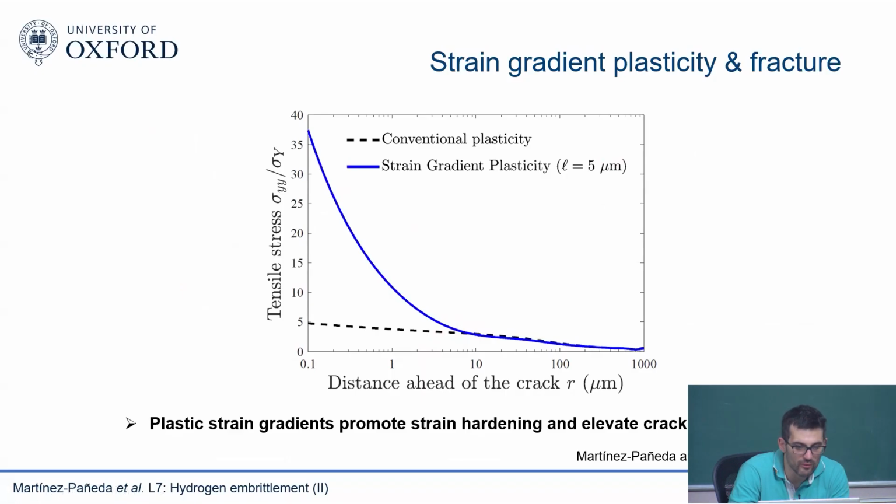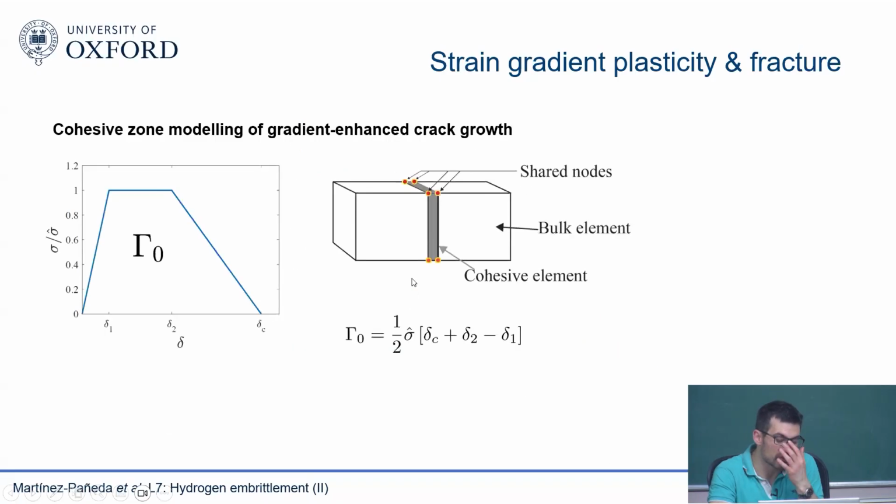Then you need to wonder, if I think of a microvoid fracture process, this is a process that occurs at very large applied load, so very large stress intensity factors. The toughness of my material is hundreds of megapascals square root meter. So this happens over very large plastic zones, and so there is not going to be such an issue. We're going to be somewhere here. That's not a problem. But it may be that you have other problems where this matters. So we decided to look into whether this could explain this idea.